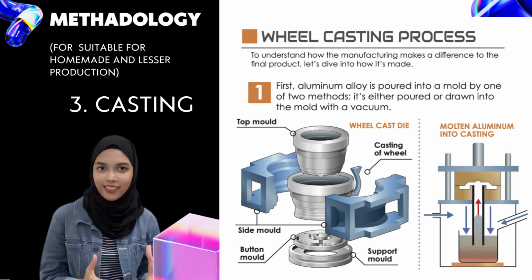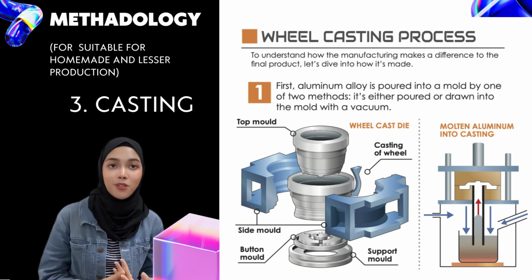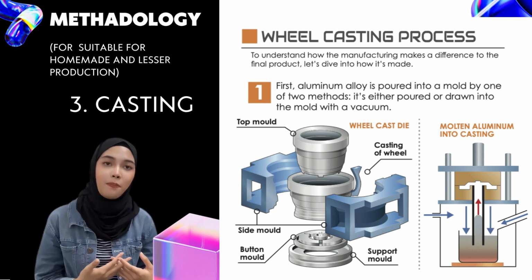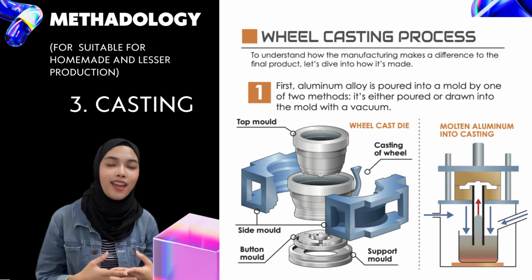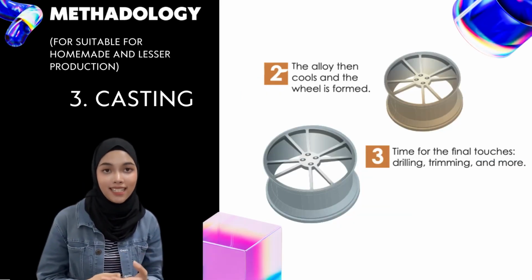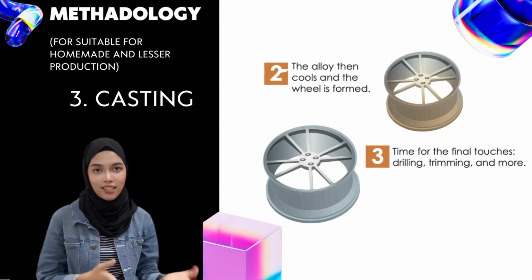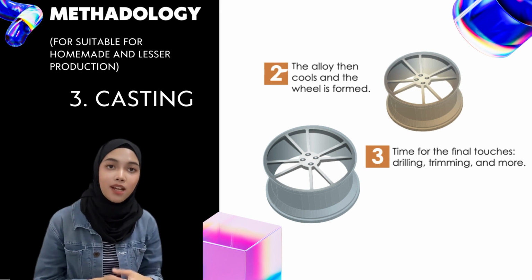So finally, let's talk about the sand casting steps to produce the wheel rim. The process begins by creating a pattern of the wheel rim, which is then used to create the mold. The mold is filled with molten metal, allowed to solidify and then removed from the mold. The wheel rim is then cleaned and finished to remove any excess metal or imperfection. The final product is a high quality wheel rim suitable for use on a vehicle.